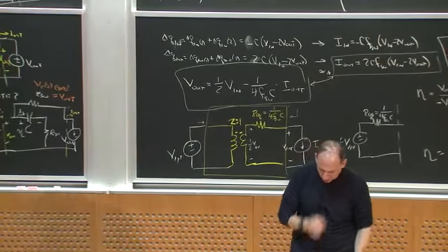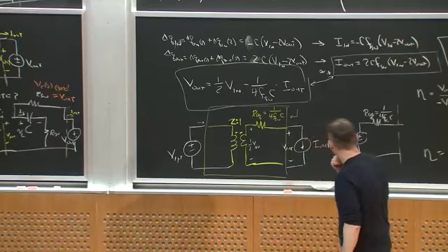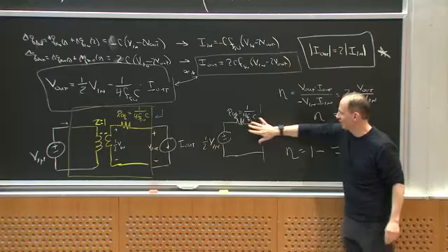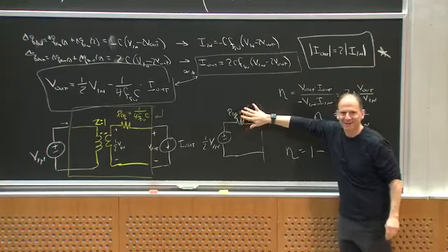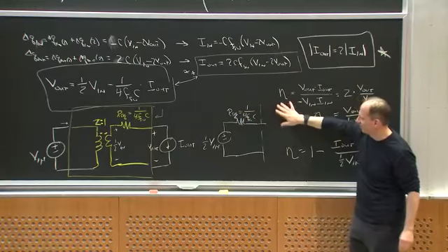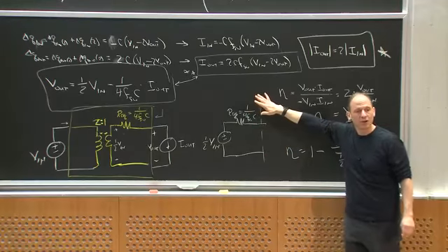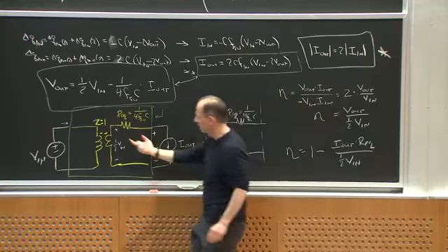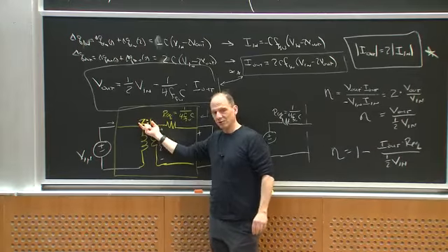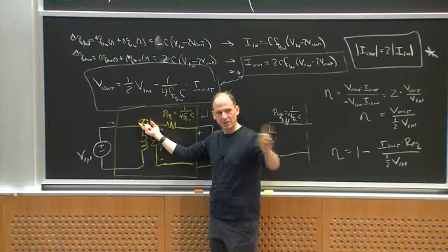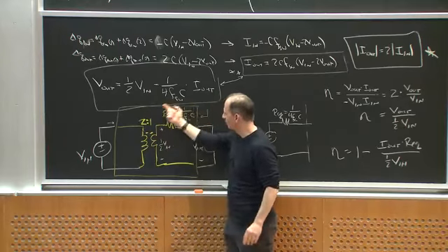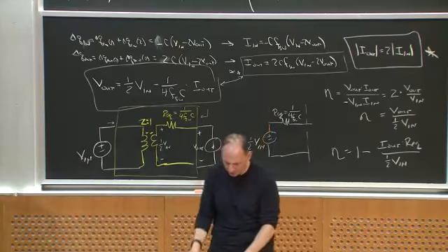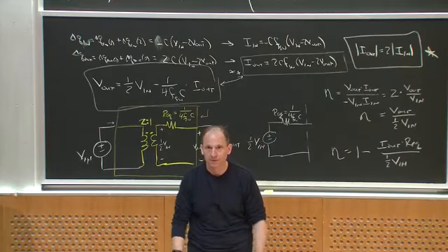Okay, so this model, in fact, if I put a resistive load on here, the efficiency is exactly just the efficiency of a voltage divider, right? So this is a very good model. And the only thing that would vary if I model any other switch capacitor converter would be this transformer ratio, which relates to that perfect current conversion ratio we calculated, and what the exact value of this output resistance would look like, okay? Which is, again, dictated by the losses. Okay? Questions?